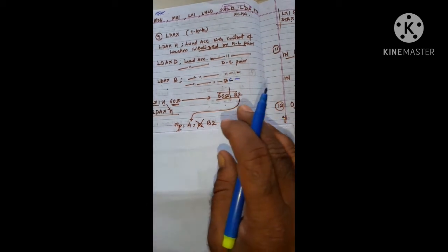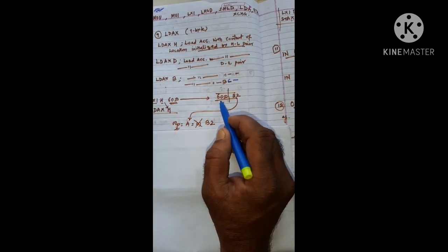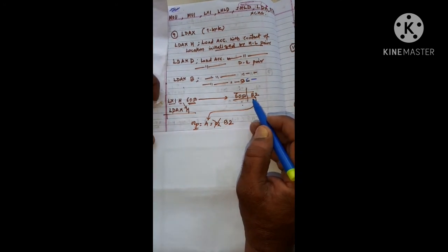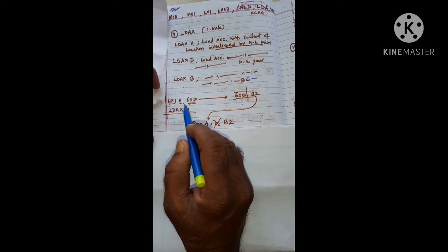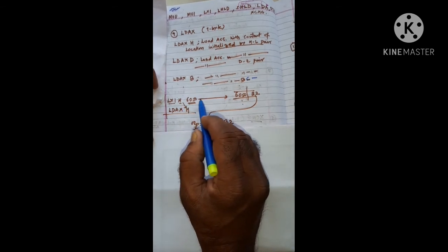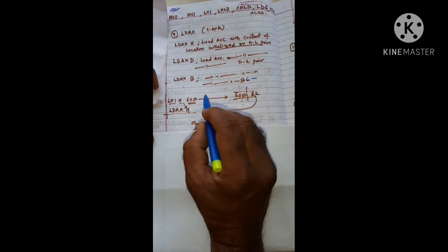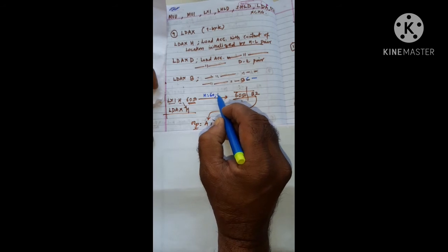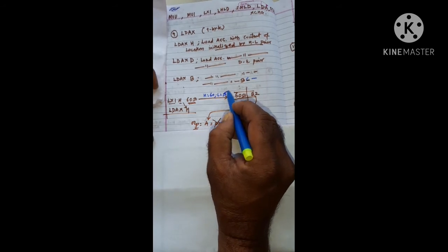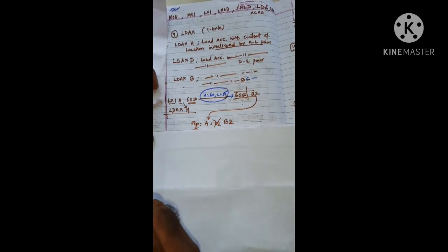Example: if on location 6050 the content is B2, using the instruction LXI H, 6050 it will point to memory location 6050 where B2 is, by loading 60 in H and 50 in L.